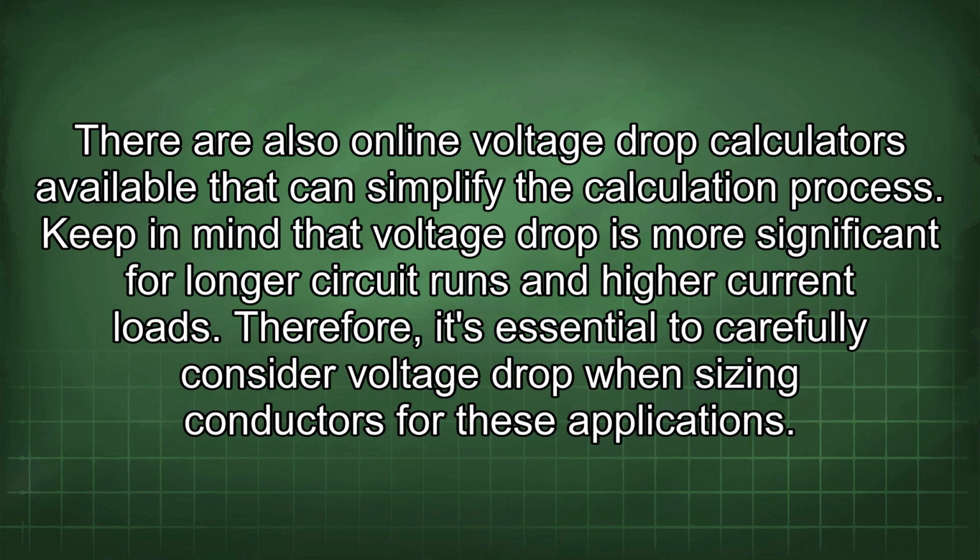Keep in mind that voltage drop is more significant for longer circuit runs and higher current loads. Therefore, it's essential to carefully consider voltage drop when sizing conductors for these applications.